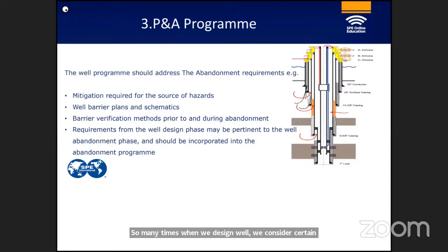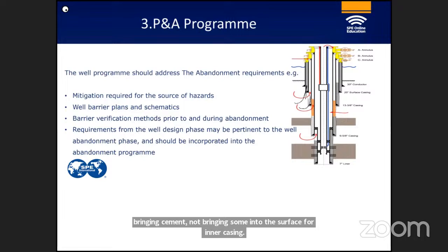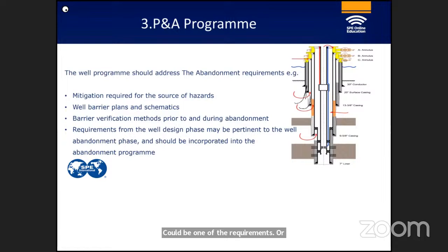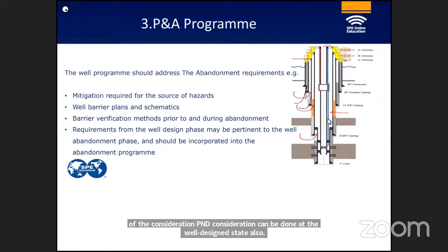So many times when we design a well, we consider certain aspects which will be required during the abandonment stage, like not bringing cement to the surface for inner casing could be one of the requirements, or not having cable to the top of the packer could be another requirement if we are doing a rigless P&A. Without complicating the situation, some of the P&A considerations can be done at the well design stage also. This is just the message I would like to convey.